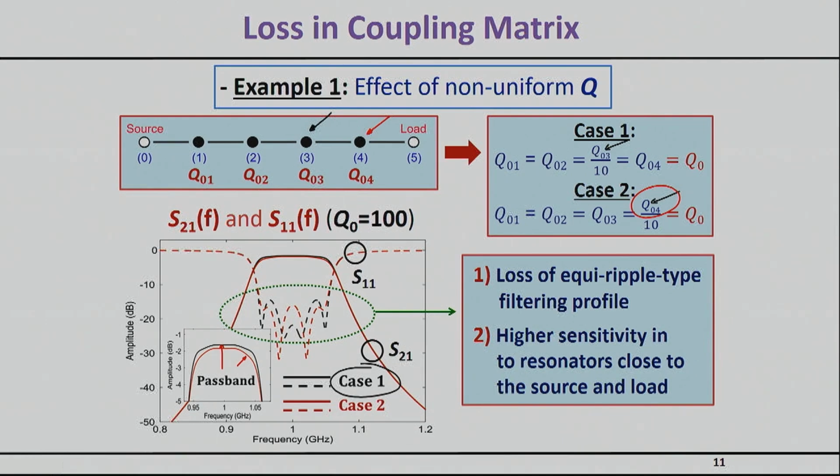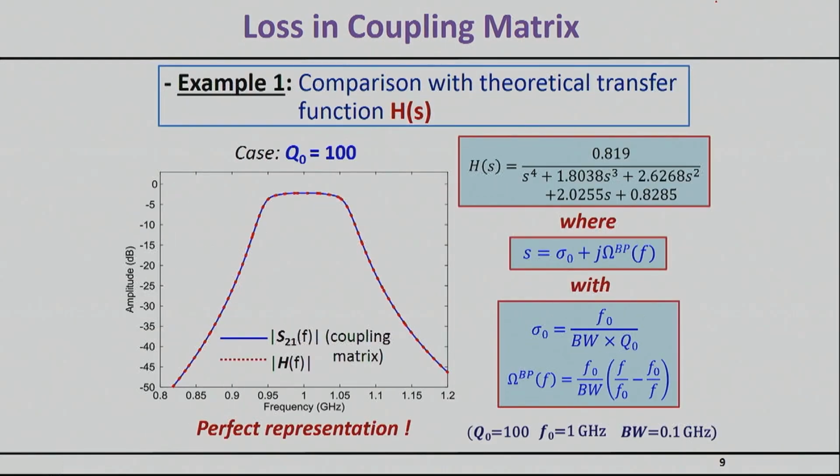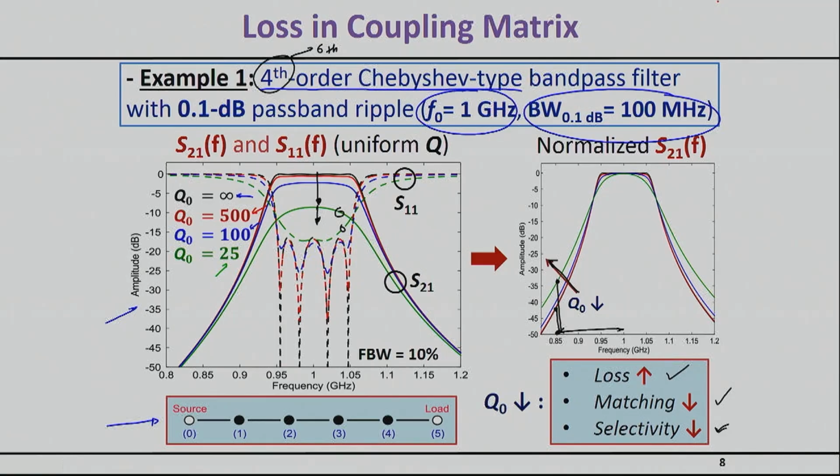Now, even more interesting than that, I think, is the question of why people might bother about creating uneven Qs. This essentially has to do with fixing the transfer function. What I mean by that is, as you might see here, when you penalize the Q, you destroy the transfer function of the filter by penalizing its selectivity. By unevenly distributing Q, you can get some of this back.